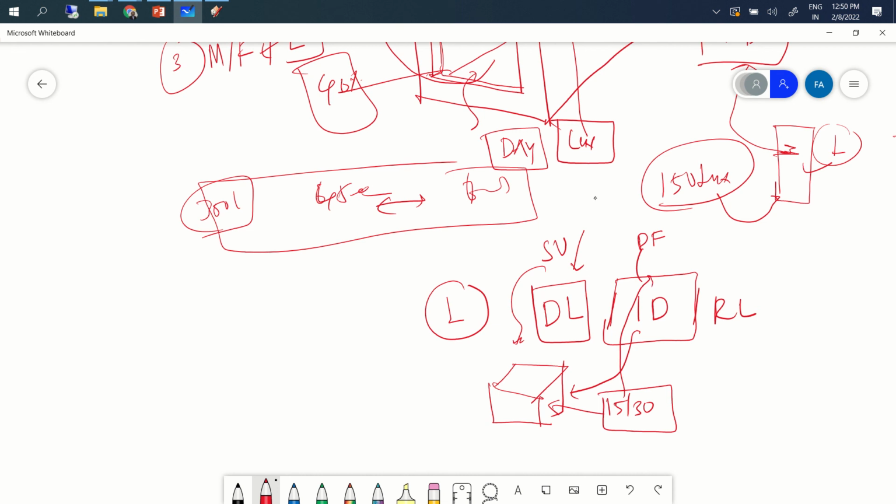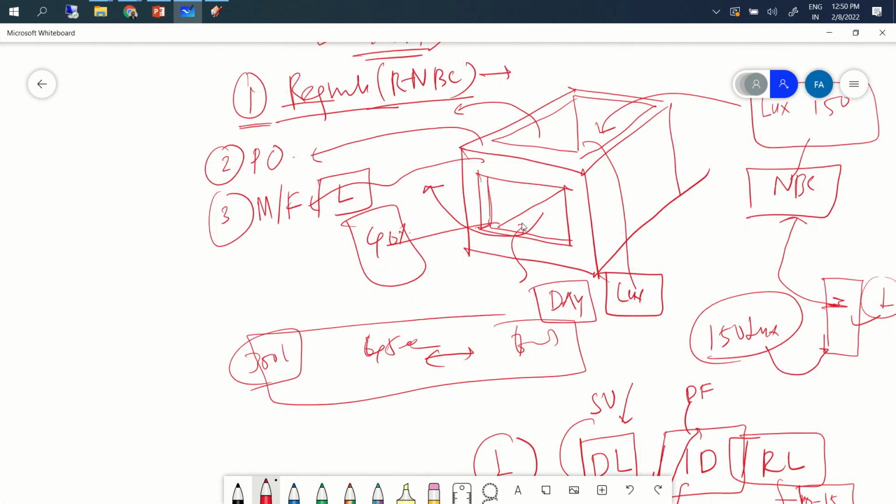And there's a third component of light, called reflected light, which theoretically constitutes about 10 to 15% of the available light. Depending on the kind of wall finishes and floor finishes we have, this reflected light will vary. So we should know what material and finishes we have.